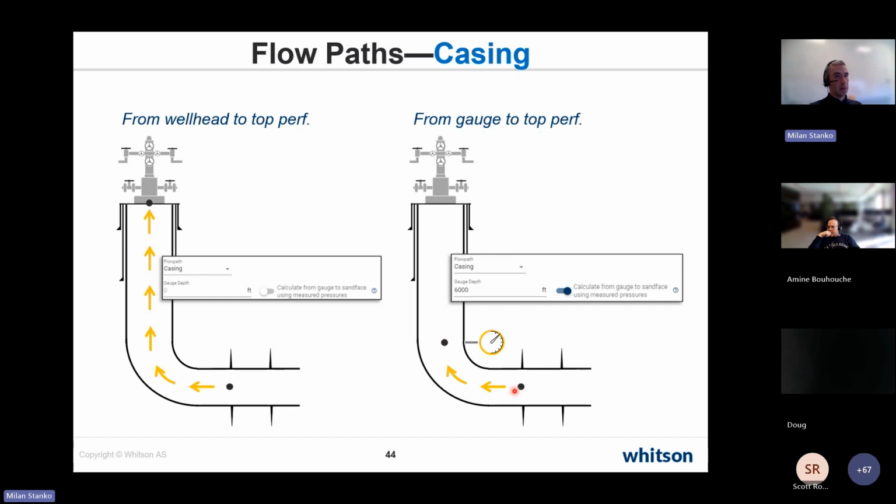Sometimes that's desired, especially since we are doing an integration procedure. We're calculating pressure by first dividing the path into steps, let's say 50 meters or so. Then we calculate the pressure 50 meters below, and 50 meters below, and so forth. So if the correlation is not very accurate, that error is going to compound and add up, and at the end you may have a big error.